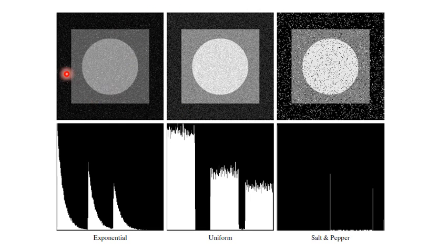Same, you can see here the test pattern affected by exponential noise, and you can see the exponential pattern in the histogram. Same way with the uniform noise distribution, you can see it's almost uniform, and then the salt and pepper noise, how the histogram will look. So this is the result of the histograms due to the adding of the noise, along with the input test image. This is how you can observe that when you see the histogram of these different images, you will get some idea about the type of noise that has affected that image.